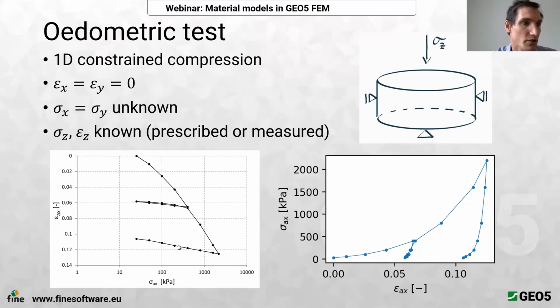Sometimes this test is also called a consolidation test, but I am used to using the word consolidation for a coupled problem where there is some pore pressure dissipation and it's a time dependent problem. So this test is not time dependent. Of course, it is measured during some time, but we assume that the pore pressure is known or 0.